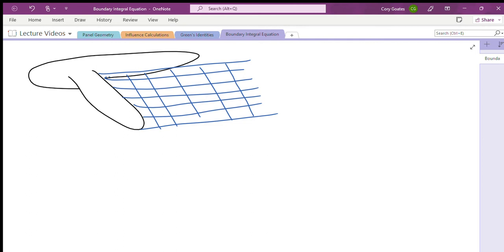So now the wake surface is a boundary. We have the region that we're interested in on both sides of that boundary. Unlike on the configuration, where on one side we have the region of interest, and on the other side we've got that fictitious inner potential. On the wake, we have what we want to look at on both sides.